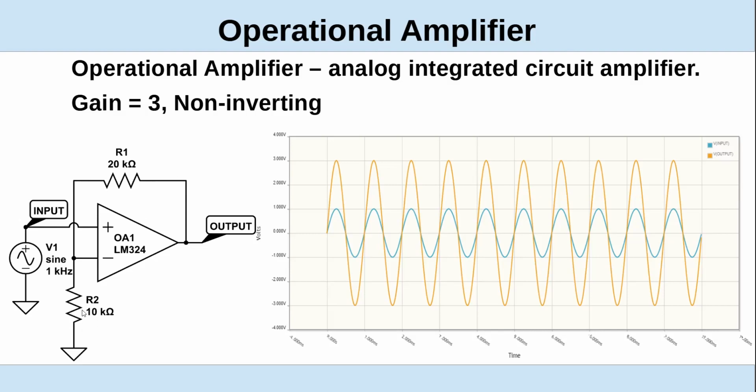Okay. 20 and 10 is 30 ohms, and we're at 10 ohms, so we're 1/3 of the divider. So if I've got 1 volt coming in on the input, when this output gets up to 3 volts, I'll have 1 volt on this side and they'll be balanced again.